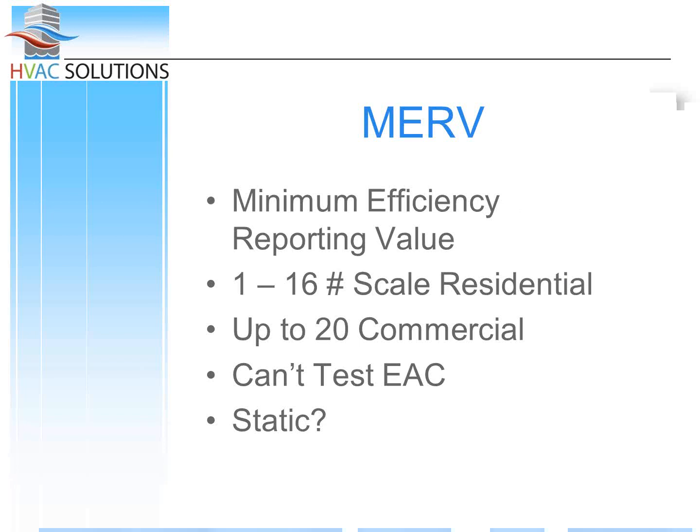Now, it's hard to appreciate where MERV has taken us without going back in time a little bit. Before the MERV rating, ASHRAE had 2 different tests. The first one I'm going to talk about is the arrestance test. This was a test where you would take a used can of coffee grinds. We call it carbon dust. And you shoot that dust through a ductwork and the filter catches it.